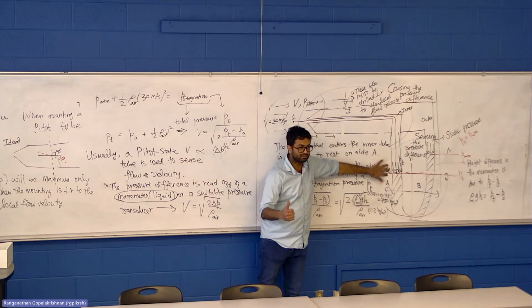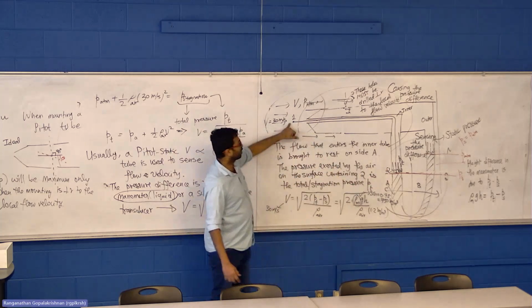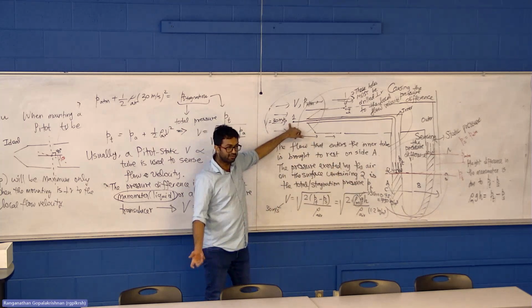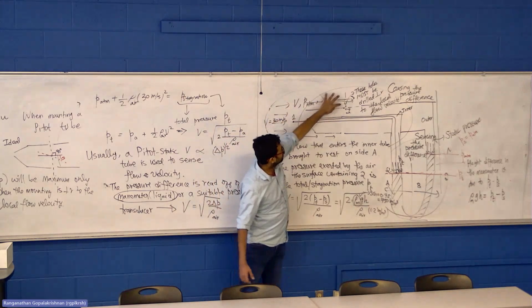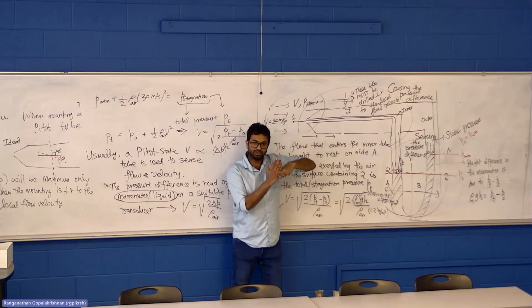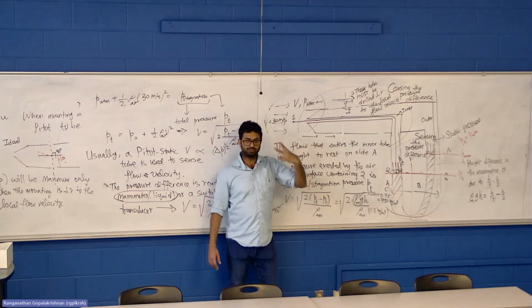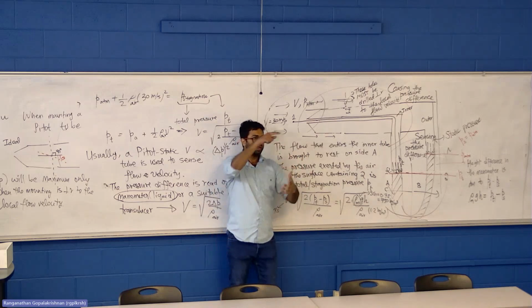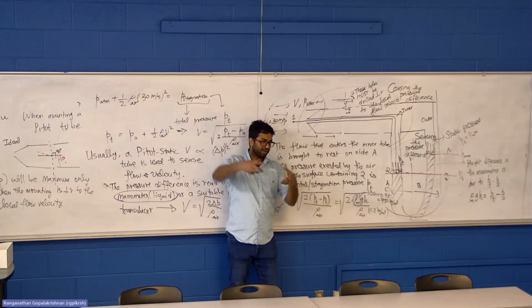With me so far? Now, if only you knew what the static pressure at point 1 is, then you can calculate the velocity. You do that by letting the flow go past, but trying to sense what happens in the transverse direction. You do that by drilling holes on the outer tube. There could be 2 holes, 4, 8, any number of evenly spaced holes around the circular periphery in a real device.